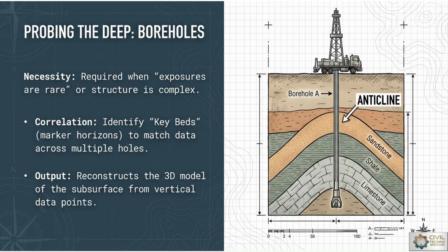The collected borehole data are extremely important for designing deep foundations for dams and tunnels. With reference to the beds of soil or rocks available, the key beds are marked to match the data across multiple boreholes and compare the data from those multiple boreholes.